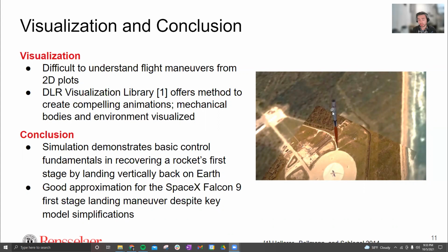In this example, this is a little screenshot of the simulation. We have the ground modeled, Cape Canaveral below here, and we have the first stage modeled with the grid fin. If this were to play, as it did when we first created it, we have this engine thrust down here, which will expand and contract based on what the engines are doing. With more thrust, it will elongate, and the grid fin angle will rotate corresponding to what the flight controller tells it to do. It's good visualization and tells what the rocket's actually doing, and you could place cameras around it to track this in real time. You can even potentially put on a VR headset and track this as it's coming all the way down from orbit, landing at Cape Canaveral here.